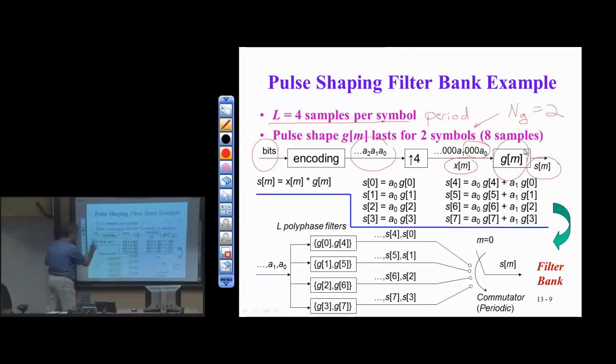So if I look at this convolution, I'll do a flip and slide of my X of M, which is now 3/4 of the time 0. So I'm going to flip and slide X of M about G. G is my FIR filter. It's a tap delay line. I do my flip and slide. As I flip and slide, every time I slide 1 point over, I end up multiplying. So what's the first value? S naught, as I show here, if you flip and slide, it's going to be A naught, G naught. Okay, that's fine. Not wasting any work here.